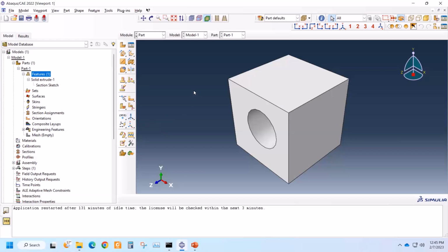Let's say if you want to do some operations not on the surface but somewhere inside, you may have to create a datum plane. And there are other tools available. We're just covering the ones that we will use most frequently, but from time to time, some of the less used functions might be needed. We'll touch base with them as needed.